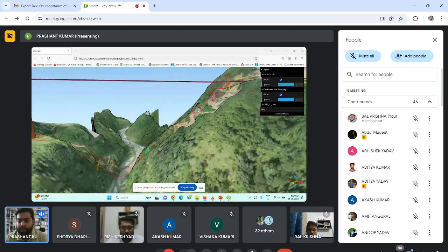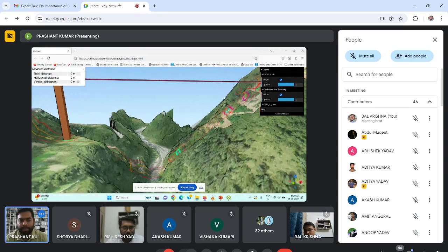But if I show you the distance from here to here, you see 248 meters. So constructing a single span, as that guy would have pointed out earlier, the distance is also a very critical point, as is the type of structure being put there. A cable stayed bridge, as I replied, could be constructed there, but there are logistic issues with it, transporting the stay cable and all these things there. So a foundation had to come in between.